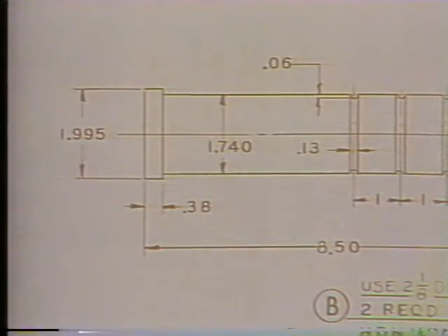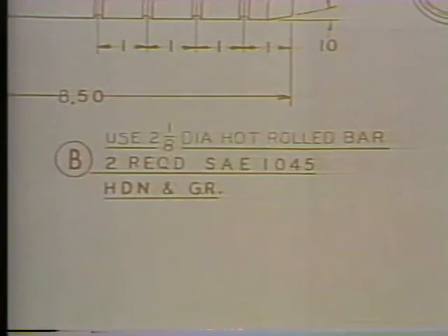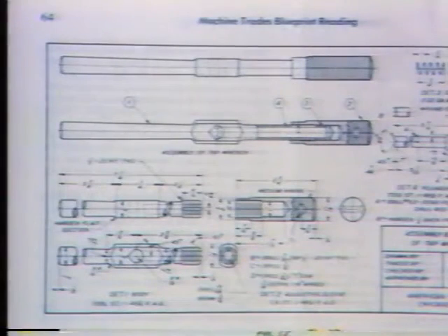Included in this information will be all dimensions, the type of metal used, the fabricating process used, and any special processes or requirements that must be followed. An assembly print can be any of a number of different prints whose objective is to make it clear just how to assemble a machine. In a set of assembly prints, there will usually be sub-assembly prints that explain how parts of the machine must be assembled.